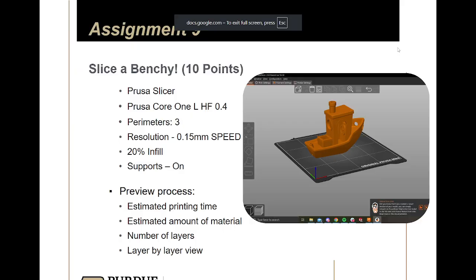No? Okay. All right, so now that you kind of know how to slice and you know the general parameters on how to do that, I'm going to talk a little bit about the limitations to 3D printing, right? We talked about supports a little bit, but there's a bunch of clever things that you can do to modify your design and make it easier to print or print better, right? And you're typically designing these things around the limitations of your manufacturing process.